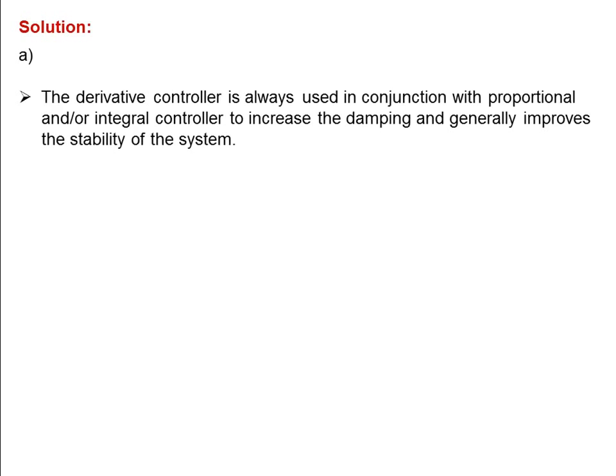For the first part, I need to mention that the derivative controller is always used in conjunction with a proportional or integral controller to increase the damping and generally improve the stability of the system.